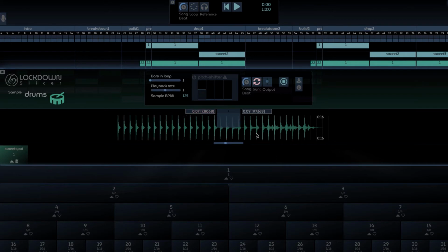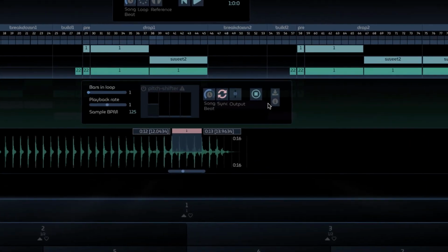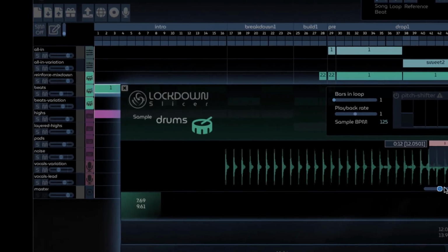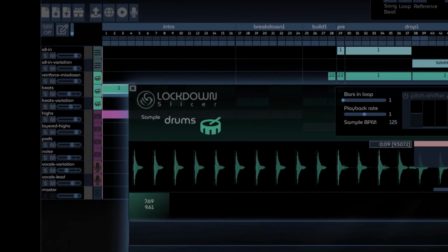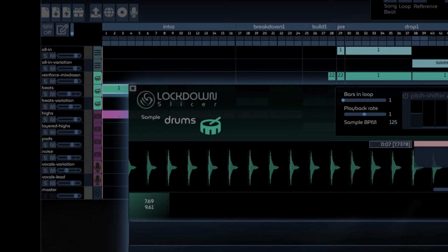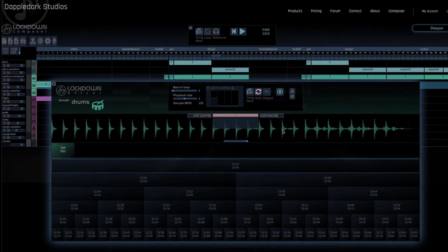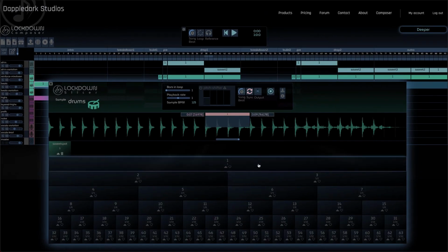If you look at this eye here, it will show you all the slice info. Here, for example, you can see changes to the transient slices as I move the wave, but the lock slices are still the same. I can therefore easily reposition my slicer at the correct position when I finish moving around my sample. Therefore use lock slices sparingly.